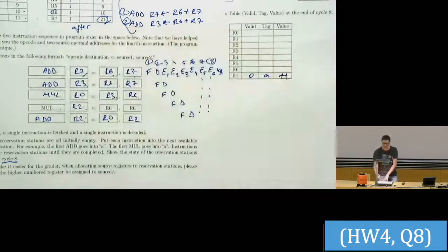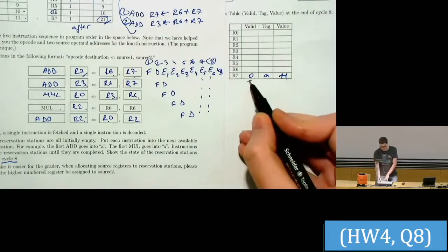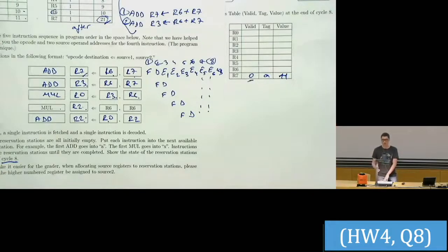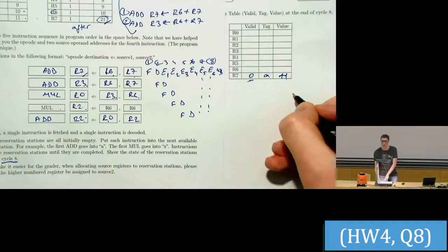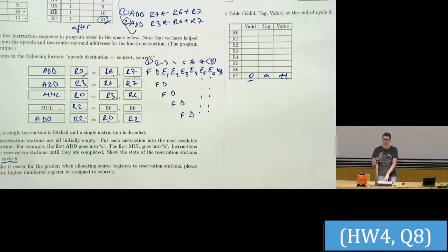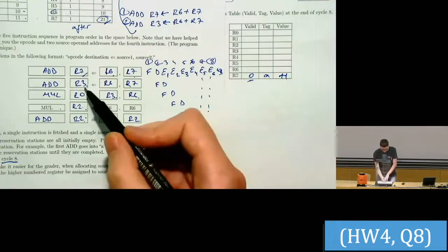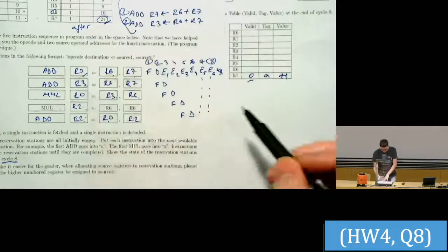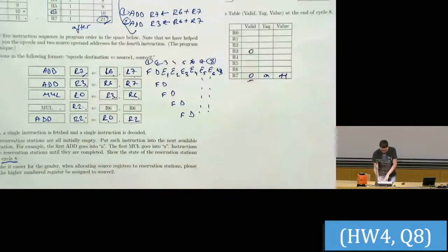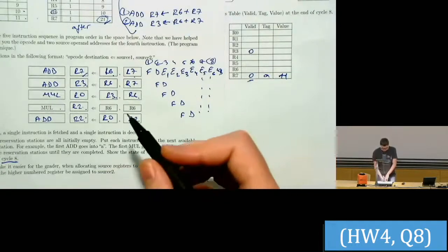But it is really a don't care value because we know that it is not valid because of the 0 here. Okay, so it is both fine to write nothing here or just to keep 11, the previous value. Okay, and then the next register we update is R3. So for R3, again, we will have 0 because none of the operations are committed until end of cycle 8.